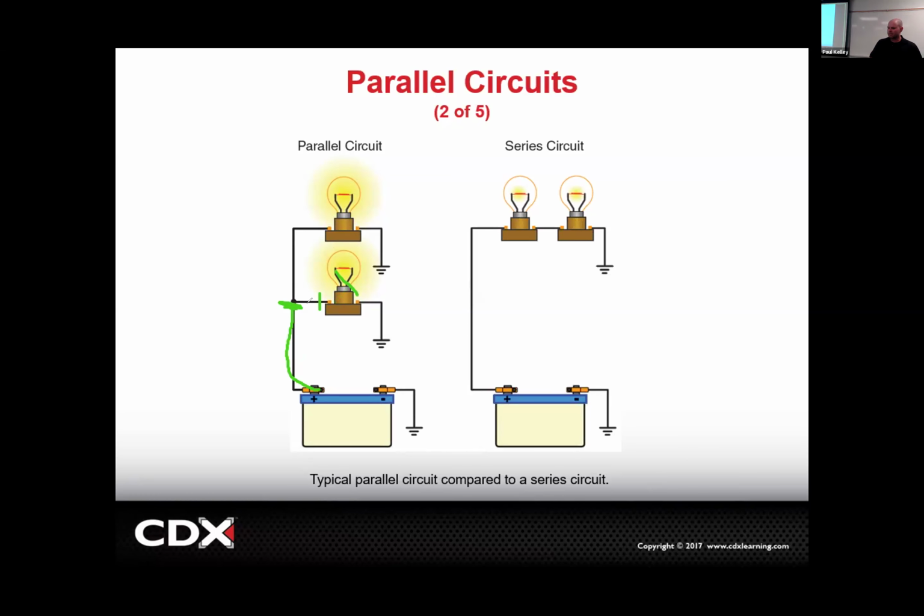So, real world application. If you rolled up to a car and none of the brake lights worked, could it be a bad left rear brake light bulb, right rear brake light bulb, and the two center high mounted brake light bulbs? You got 4 bulbs out? It's possible. But do you think there's something a little more likely? It's probably in the circuit where it's more like series, right? So that would be from the battery to the stop lamp fuse to the brake light switch and to where it tees off, right?